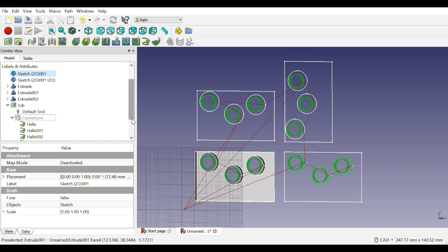Now, one thing I didn't do correctly, I still ended up creating all the helixes first, and now I'm going to go and the carving the outside edges will come afterwards. I should have interspersed these, one helix with one of these, and the next helix followed by one of these, profile based on edges. You could use contour, but I can't get it to work. I haven't tried these others. I've tried based on edges, I've tried helix, and drilling and such I don't really use.